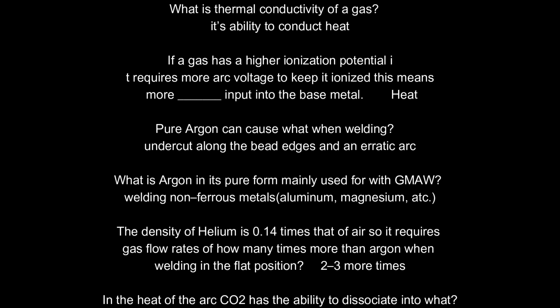This means more heat input into the base metal. Pure argon can cause what when welding? Undercut along the bead edges and an erratic arc.